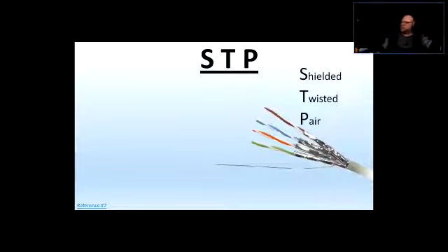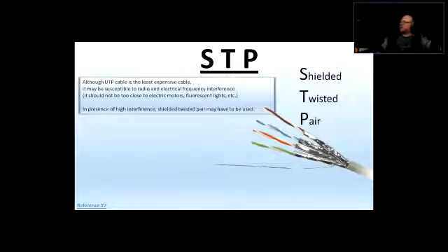So it's just an idea of you might want to research that, like a Faraday's cage, right? Because if you have a metal surface, the electromagnetic waves do not go through metal, right? So it's like a shielding, screening, so shielded twisted pair, and it looks basically like this, right? Now there are different types of shielded twisted pair cables.